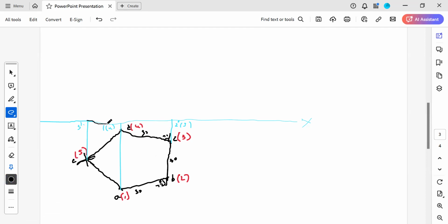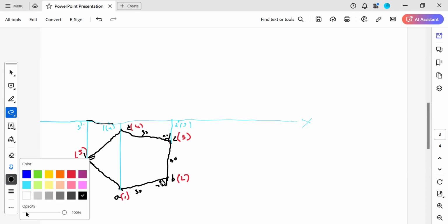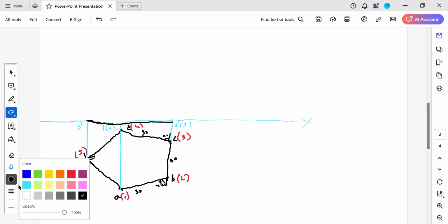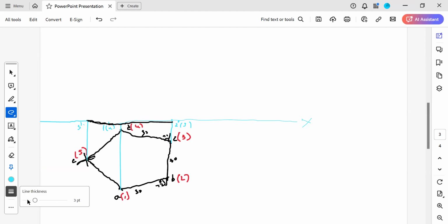So this is the width of the given line. You go here, this is the width, automatically you will get from the projections. Okay, once you got the width, now you draw any two perpendicular bisectors for the two sides. Passing through the midpoint, you draw a perpendicular line, for any two sides, you will get the center.